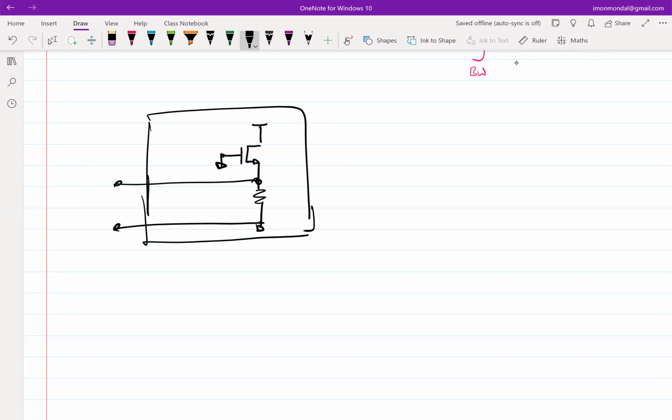You are giving this to the customer, and your customer wants the equivalent noise model looking into here, right? So the input referred noise model is what you will get. How do I go about doing it? I know that my input referred noise model is equivalent to this,